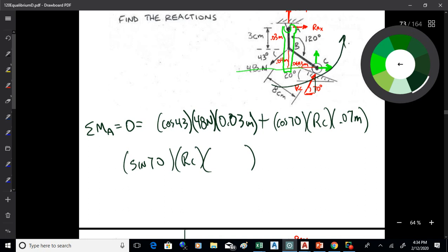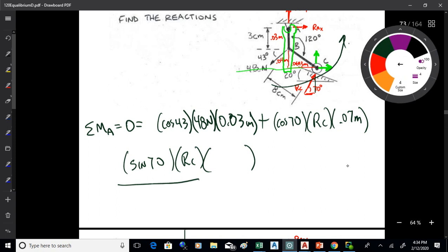Good with that? Now, keep in mind that if the component of force is an x, the moment arm is a y. They're different always. If the component of force is a y, as we see here, the moment arm will be an x. So we doing all right with that? I think it would, because what you're doing is you're coming up and around like that. And again, if you have doubts about this, there are lots of little tricks to use. Push on your paper, draw an arrow that circles around the point, whatever works for you is fine.